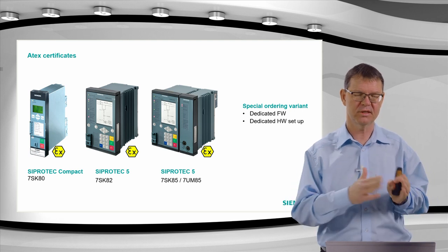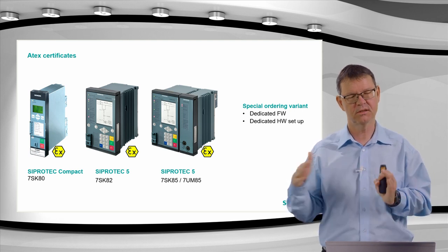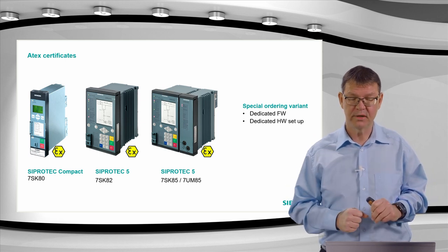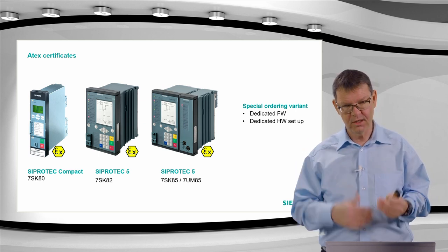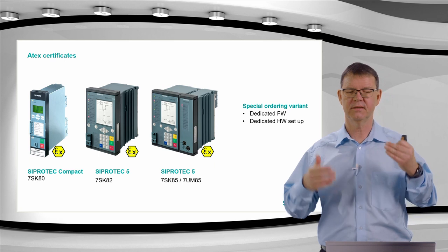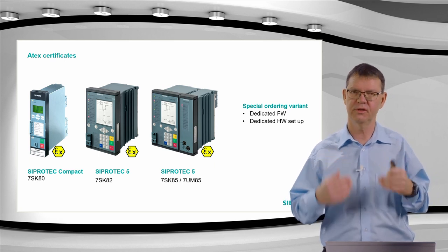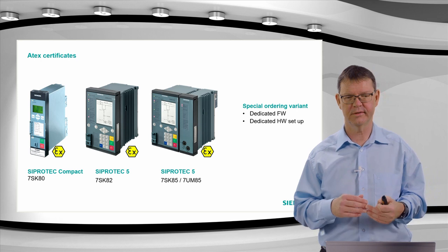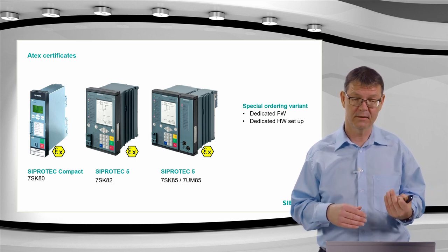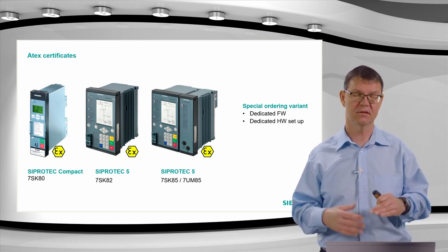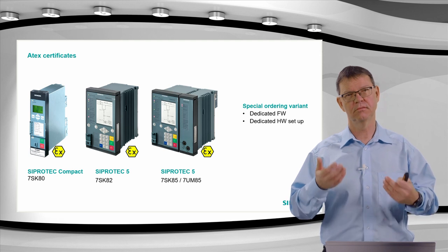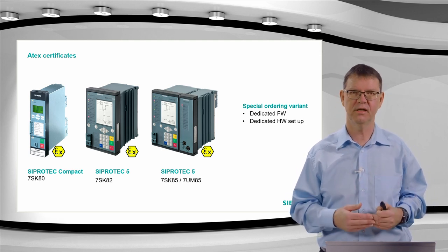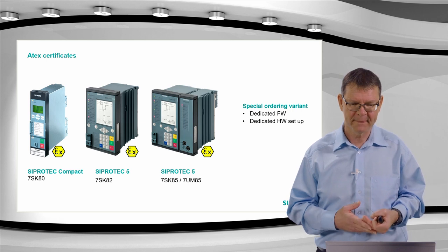So we made some setups from just a smaller device to a bigger one with more IOs, for which we calculated these failure probabilities and for which we then started to prove that we fulfill all these ATEX requirements. Basically what is behind this SIL level 1, which we must fulfill, and in this SIL level 1 there's a certain number or rate of outages or device failures which we must fulfill.